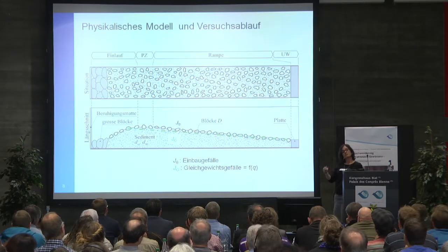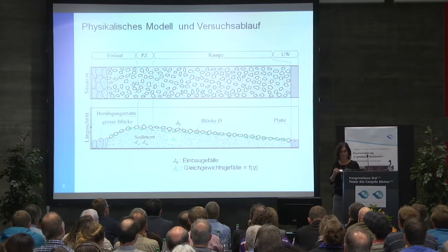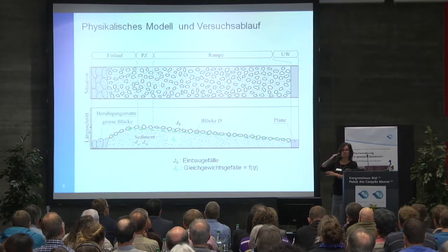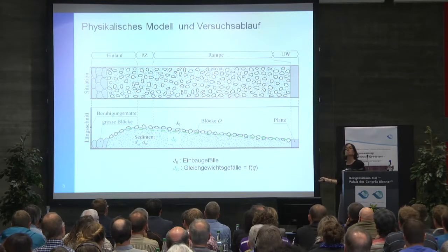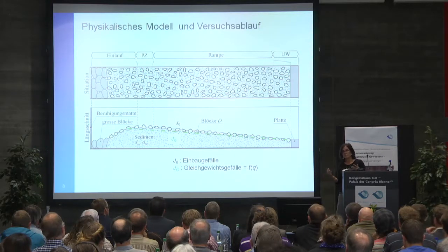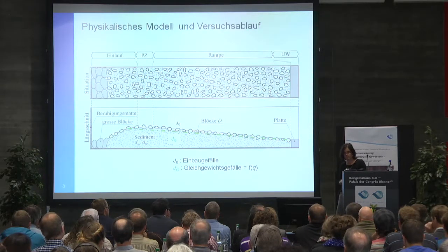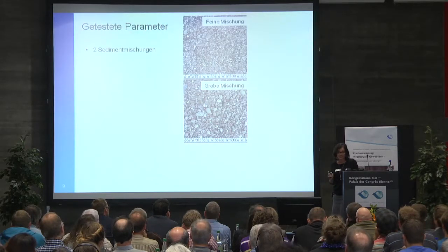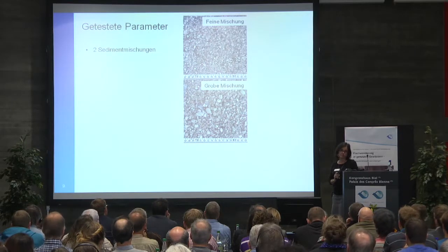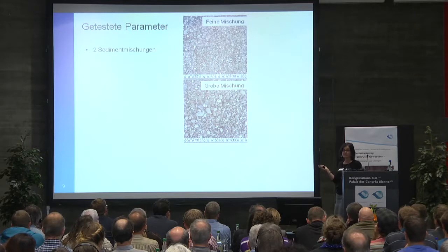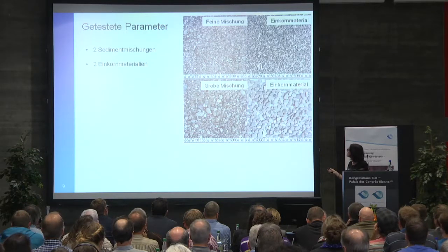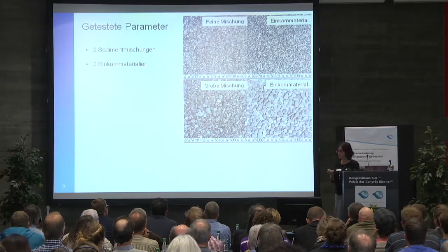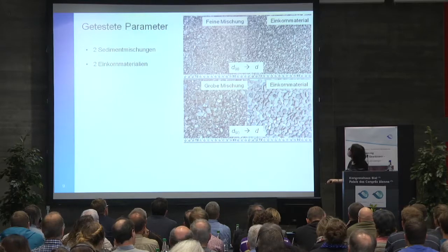In that case, I measured the slope again, and in the next step, we took a higher flow rate. So we were able to assess the erosion in the ramp, and for every load case, we were able to determine the balanced slope. As we said before, we wanted to determine the optimum situation for 2 different sediment mixtures, fine and more coarse, in line with different regions.